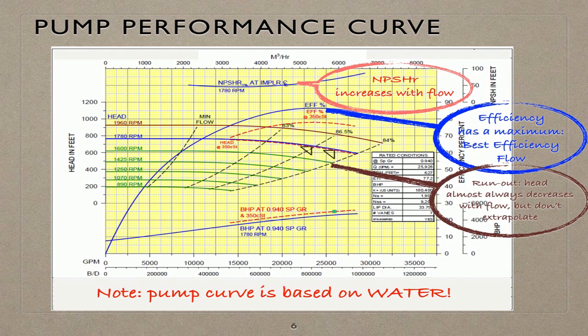As we can see, pump head almost always decreases with increasing flow rate. In this curve, the last point is the theoretically maximum head possible. This is true, but only in ideal cases. In practice, there are a lot of energy losses associated with pump flow, so this maximum head cannot be reached.